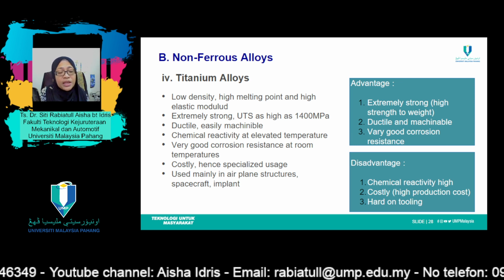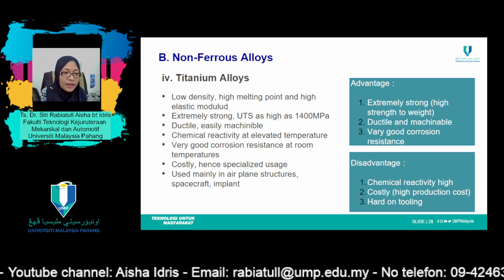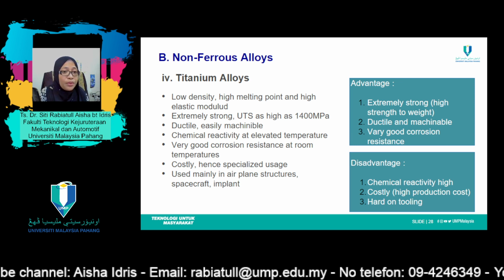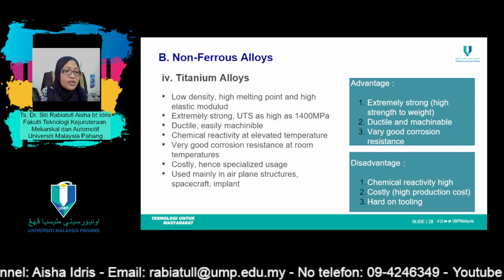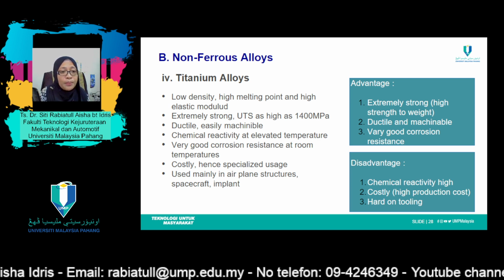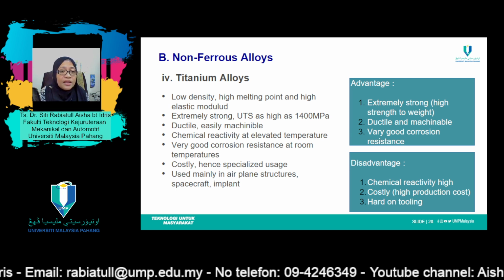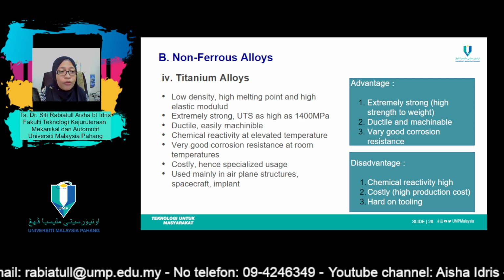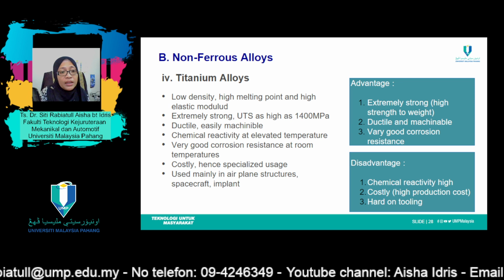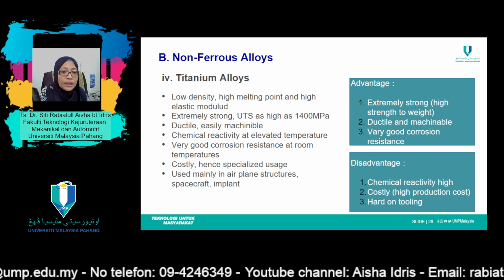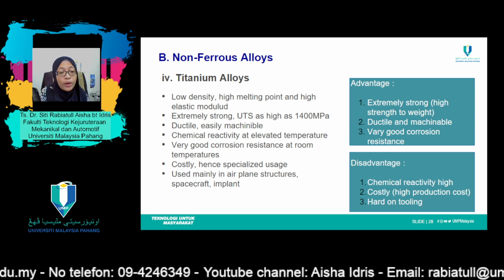The major limitation of titanium is its chemical reactivity with other materials at elevated temperature. This property has necessitated the development of non-conventional refining, melting, and casting techniques. Consequently, titanium alloys are quite expensive.